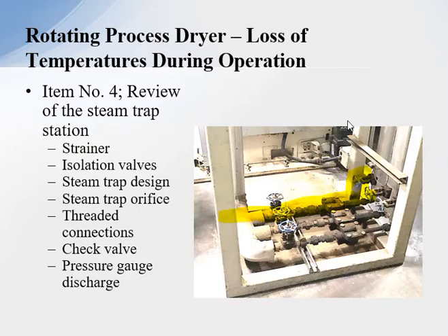Next we looked at the condensate drainage side, and this is the condensate coming down here. There is a strainer here, but the strainer did not have a blow-off valve on the strainer. We had to shut the system down and take a look at them. The strainer was probably around 35% plugged, which was restricting flow coming to the steam trap.